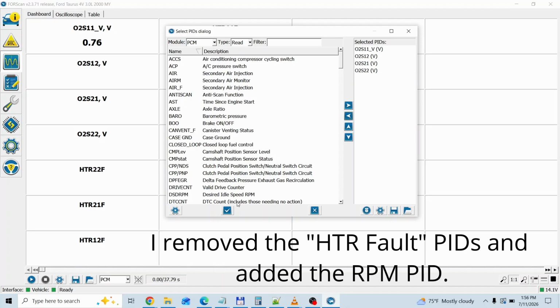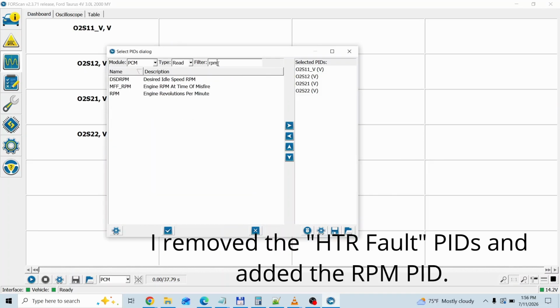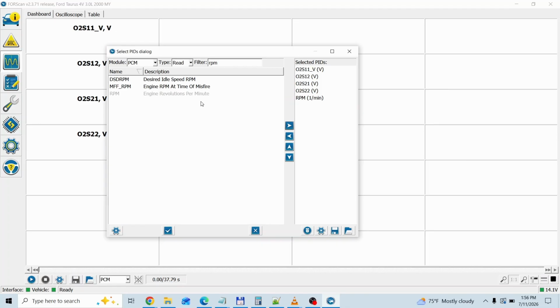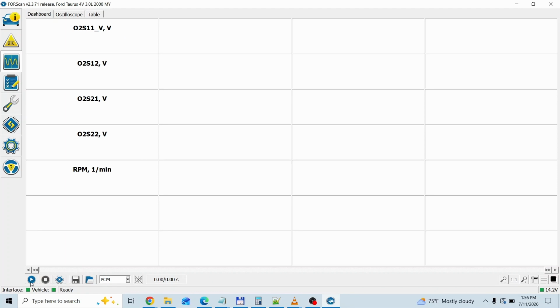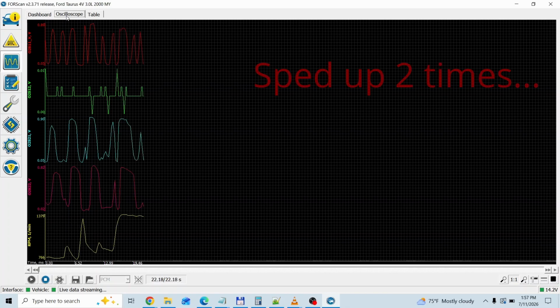Though one thing I want to add at this point is that, despite having this information of the voltage not being correct on the output of this O2 sensor, I can't really conclude that the issue really is with the O2 sensor. I don't know, perhaps another situation like a shorted out wire could cause the same kind of condition, maybe. But at this point I decided that I'm just going to change out that O2 sensor anyway, and hope that it resolves the issue.